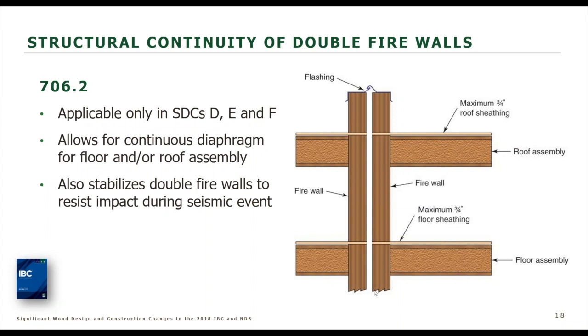However, from a structural standpoint, if there's any kind of separation, we cannot treat those two buildings as one building. So they've got to be structurally analyzed separately and with this gap. Well, this can be an issue when we're dealing with lateral loads, because now we don't have a diaphragm that runs through to make it one continuous diaphragm. So, especially in high seismic areas, where if we have two buildings together and they're treated as separate buildings, we've got to provide a seismic separation between those two buildings so that they don't hit each other in an earthquake.